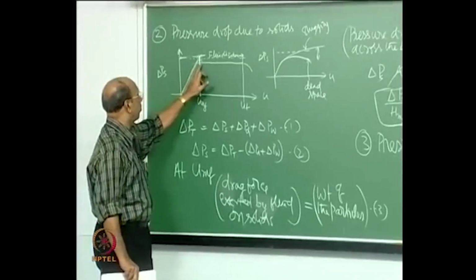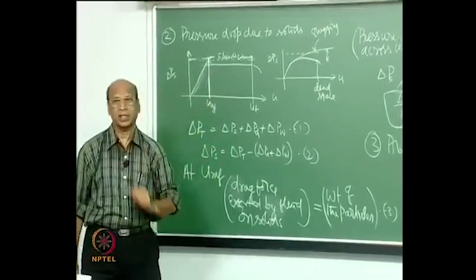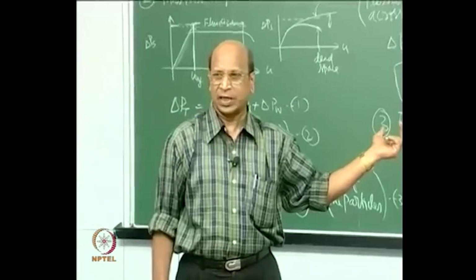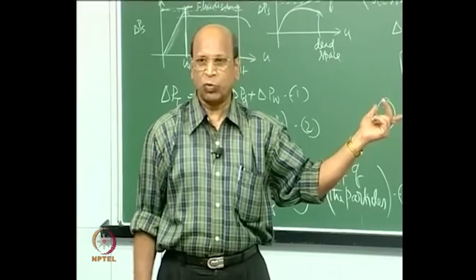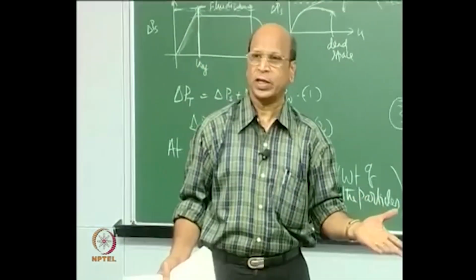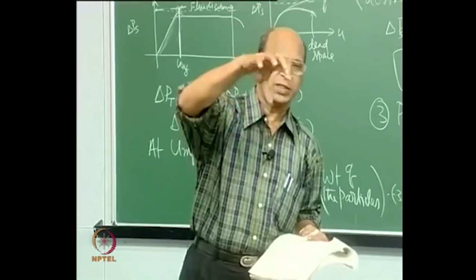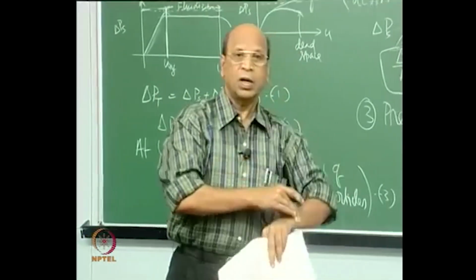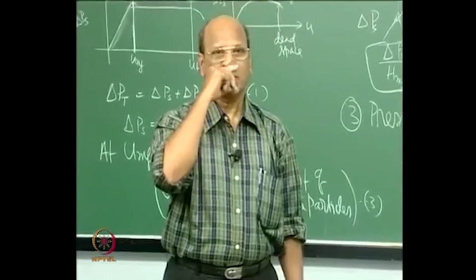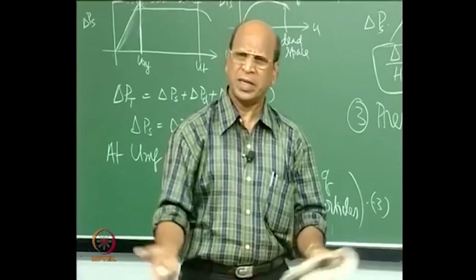And this kind of very beautiful points you cannot see particularly. By the way, this is generally for Geldart A and Geldart B particles. If you go to cohesive powders, then you cannot exactly find that nice curve. That is why we do not want to fluidize group C particles, cohesive particles, but if it is absolutely necessary, we have to do it. Then use either vibrations, or some people even use ultrasound. Ultrasound also breaks the interparticle forces. Many techniques can be used.